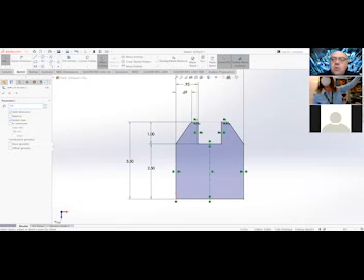Now, we're not going to do chain. Chain means that whatever lines are connected, they will all be offset. So take chain off. We just want one line. And then we've got this bidirectional option. That means it's going to do two ways at the same time. Go ahead and put that check mark on. Now let's see what that's going to do.